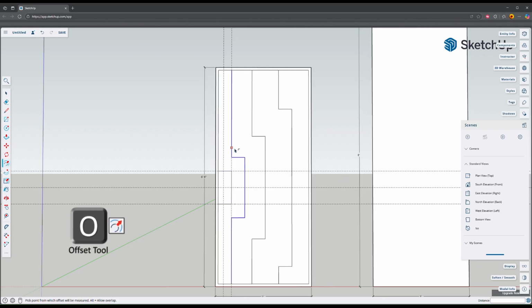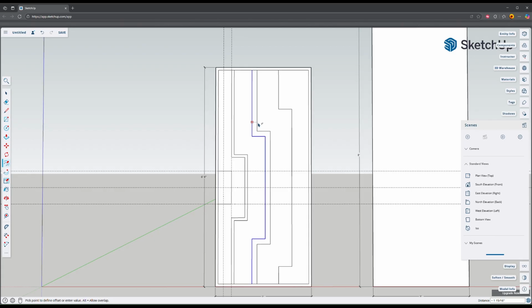Selecting the new outlines, I tap O for the Offset tool and pull 1-inch copies for each of the new panels. This will allow me to use an indented area between each panel. This should add a nice contrast between the alternating materials I plan to use. Indenting each of these 1-inch dividers will also give a nice dimension effect I like to include in my modern doors. Here I begin to lay out a window for my door.